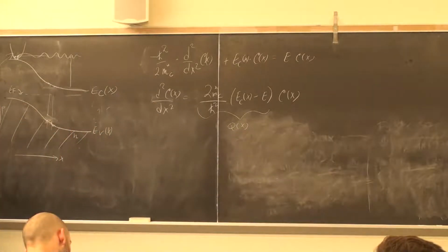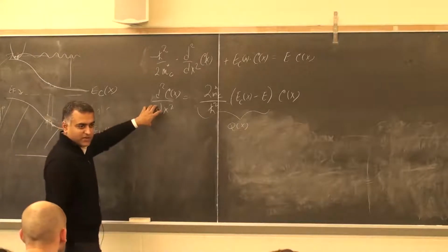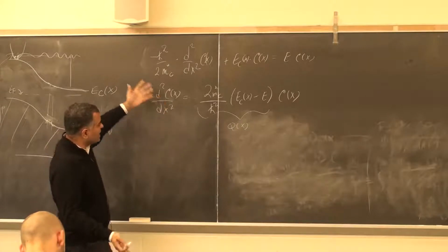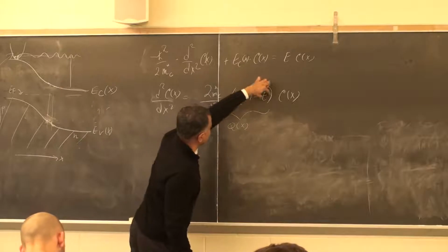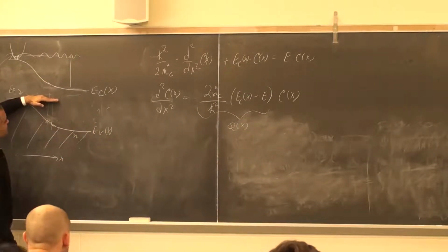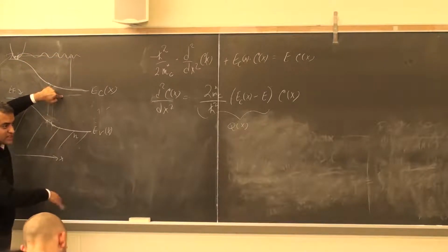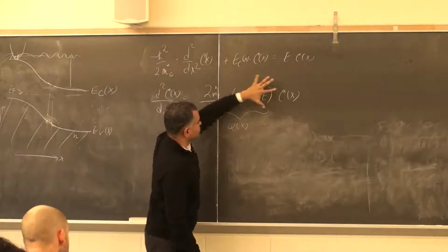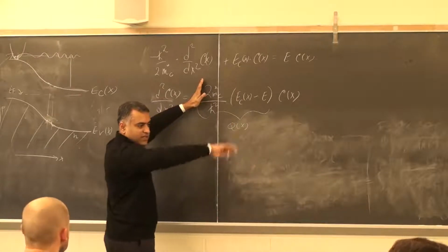We had written down the most general solution for it in this approximation form called the WKB approximation, right? In general, you can see that if EC minus E is positive, meaning the energy was lower, then it's an evanescent state. It's in the gap now, right? And in which case you have a double derivative proportional to itself with a plus sign, so it must have decay or growth, right? Does that make sense?